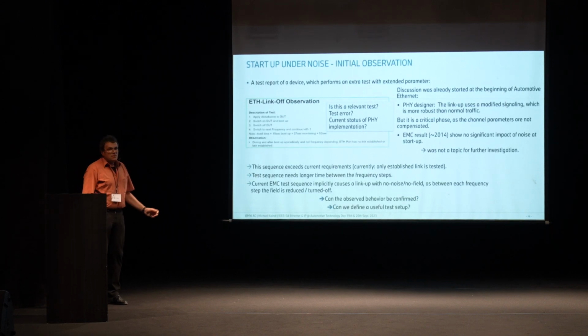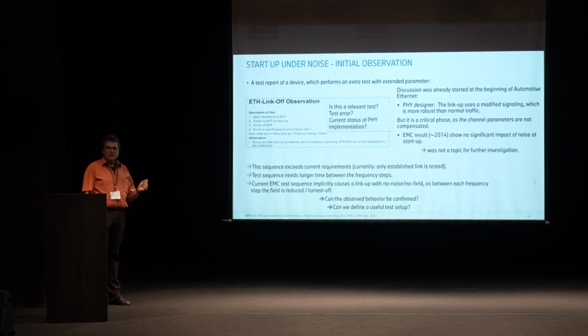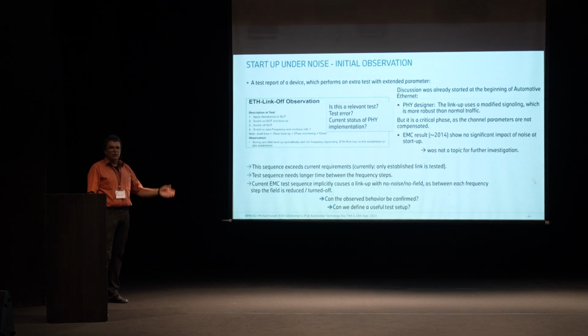The story started about 1.5 years ago when a colleague came to me and said, hey, we experienced some problems with startup under noise. I asked, what are you doing? He said, we made an extended test and used our EMC test equipment and tried to do startups there. He described it as written in this box, hardly readable, and it's very easy. You apply a field, turn off the device, turn it on under the presence of the field, look at the result, turn it off, and go to the next step.